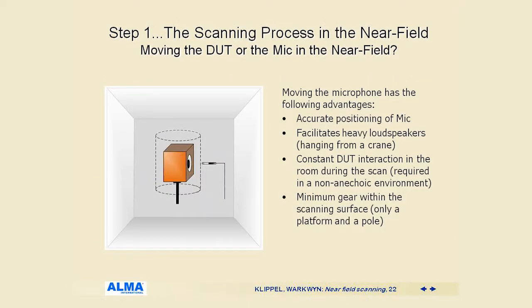Step 1, the scanning process in the near field. The question is, do we move the DUT or the mic in the near field? The advantages of moving the mic are as follows. You get accurate positioning. You can accommodate heavier loudspeakers.